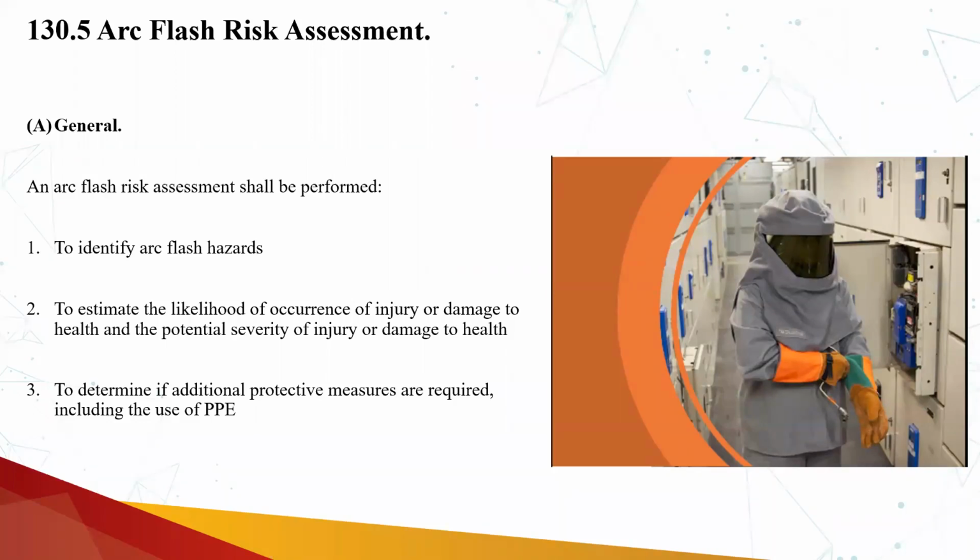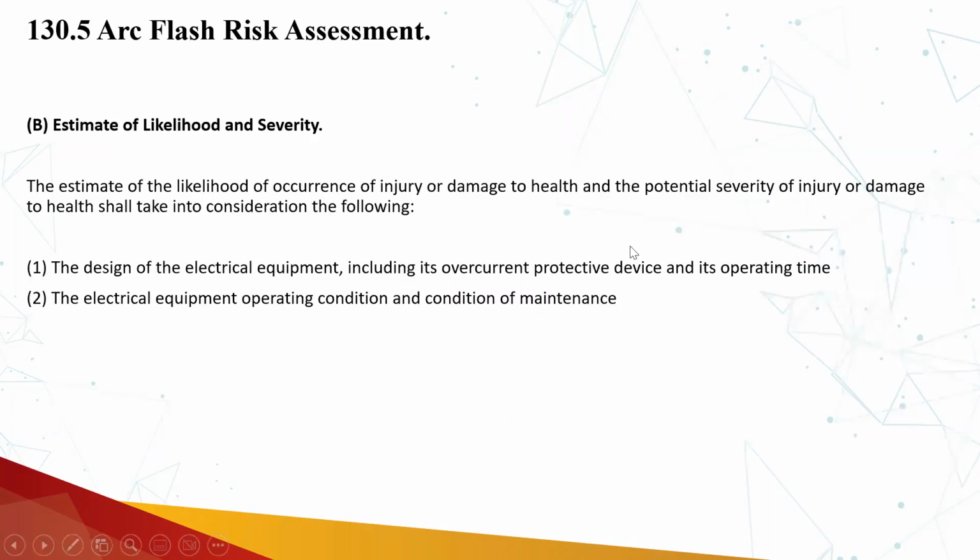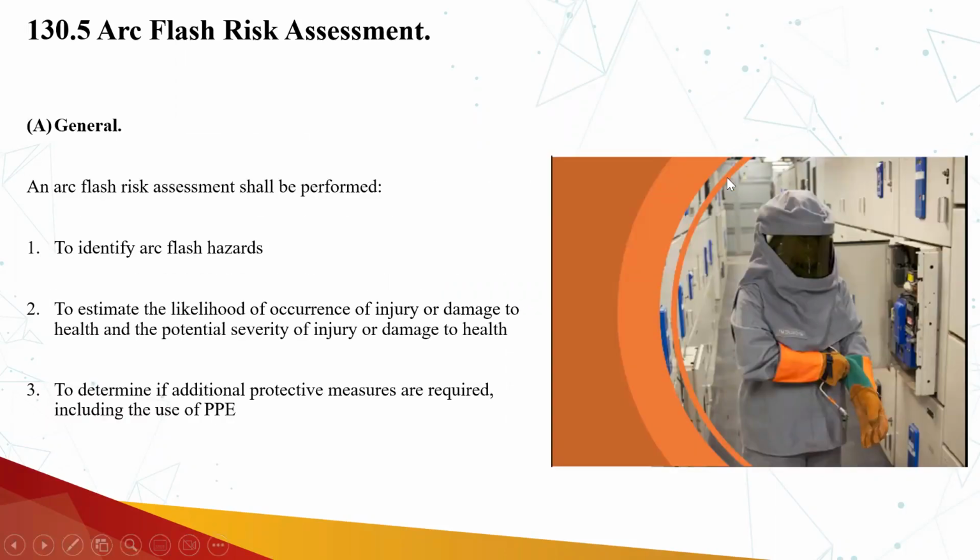So that's why the PPE mentioned here in 70E does not provide you protection against the arc blast. So what is an outcome of an arc blast? Due to arc blast, one person can be thrown maybe 10 meters or 10 feet distance, or enough pressure waves will be felt on the chest that can cause breaking of bones, or due to loud sound, deafness can occur. 70E does provide that you should be wearing hearing protection.